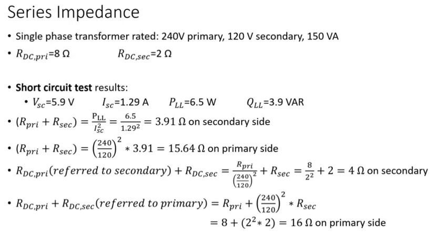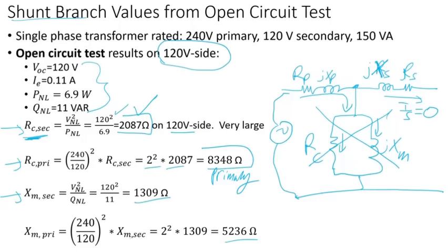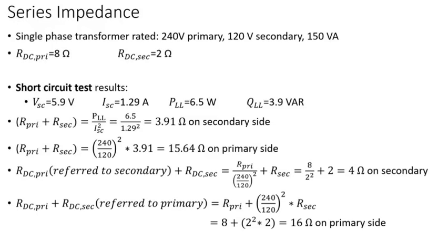So I calculate the open or the shunt branch impedance. So now we can calculate the same thing for the series branch, or series impedance.